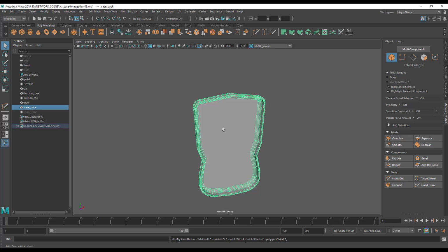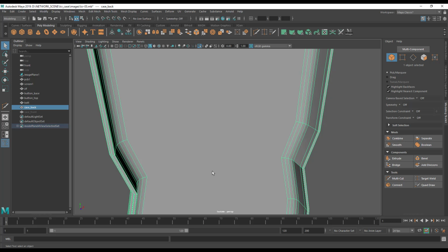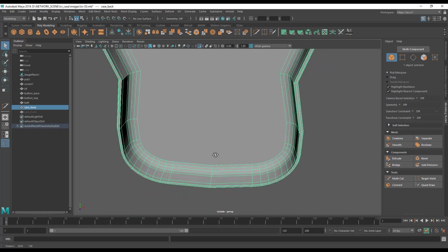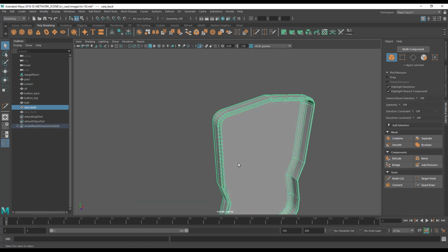But just so you know, if you wanted to quad this out, all you basically got to do is line all your edges up, cut in between, and make the relevant changes to tie edges together. In fact, I've got a tutorial on modeling a Lego car which deals with some of the intricacies of getting fairly complicated pieces and shapes into one model with quadded topology, if you want to watch that.